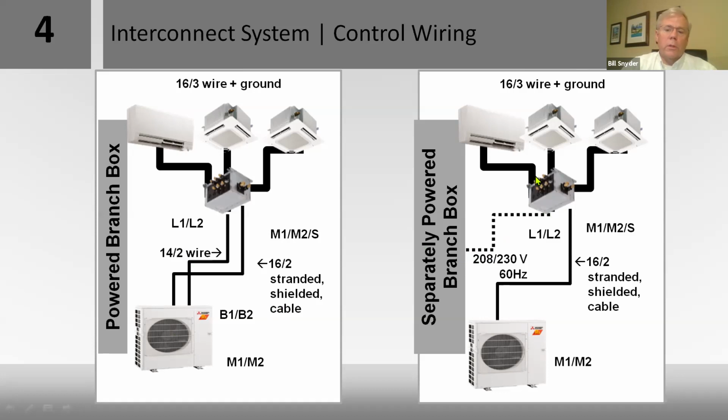Also, when you start the system up, you have to power up the indoor systems first, then go out and power up the outdoor system. If you do that in the opposite sequence, it will not run.